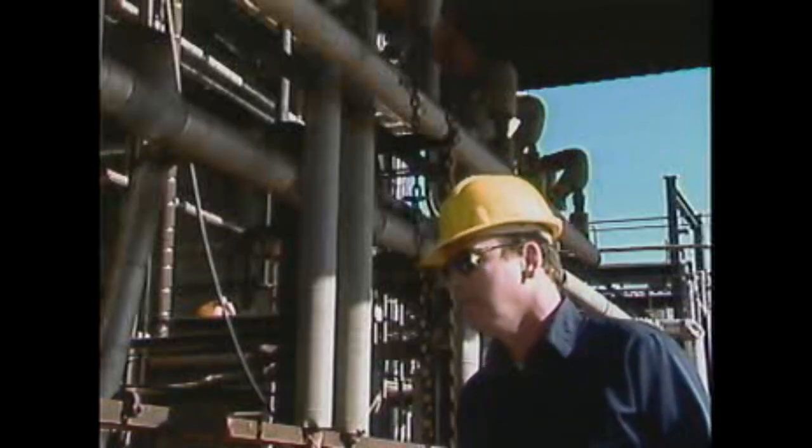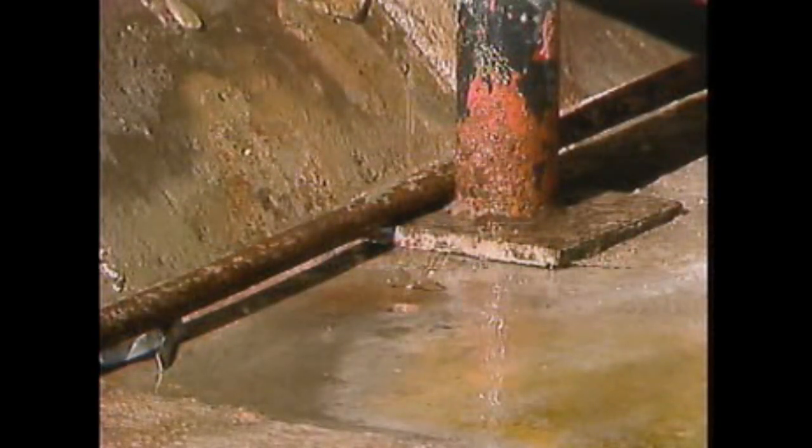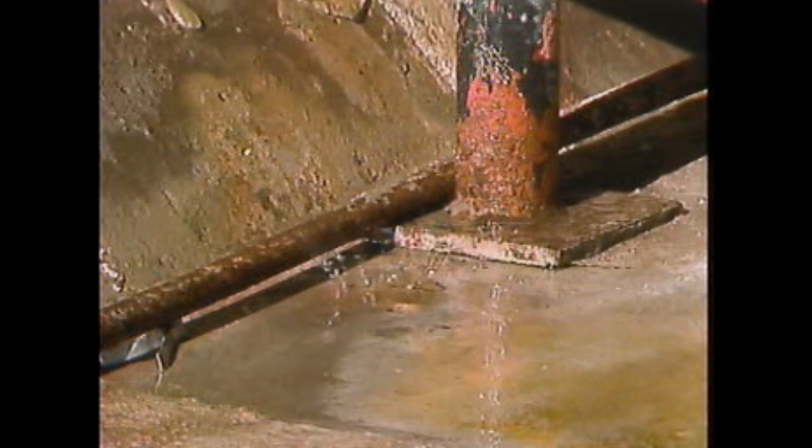As an operator, you'll probably be responsible for making general checks on fluid systems. In this part, we're going to go over some of these operator checks. We'll begin with one of the most important, checking for leaks. Some obvious signs of leaks include puddles of liquid, wet spots on piping, unusual odors, fine sprays, or puffs of vapor. The entire system should be checked for leaks.